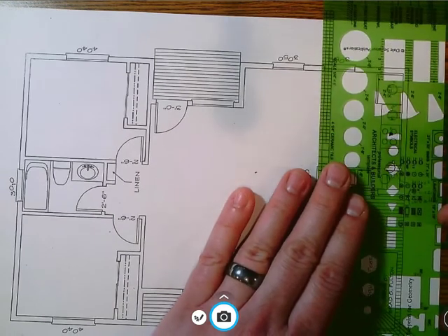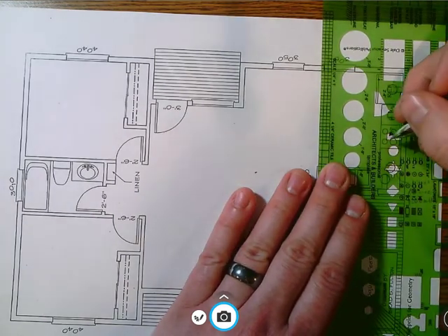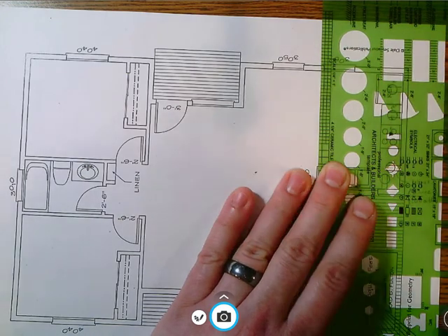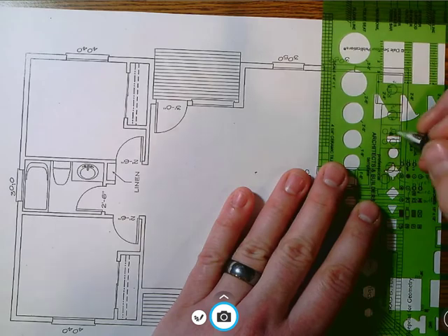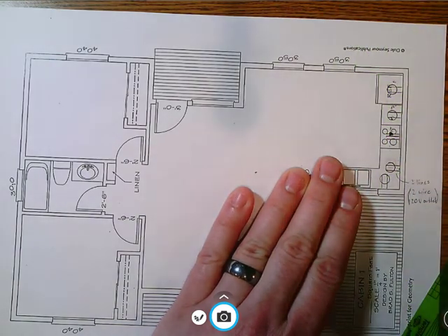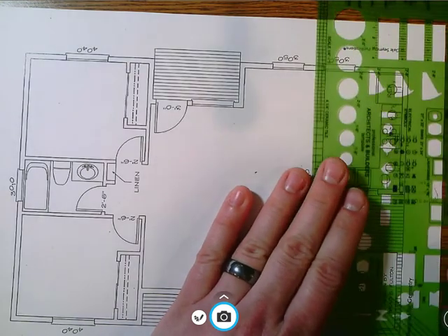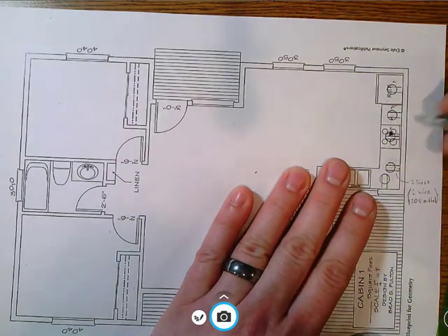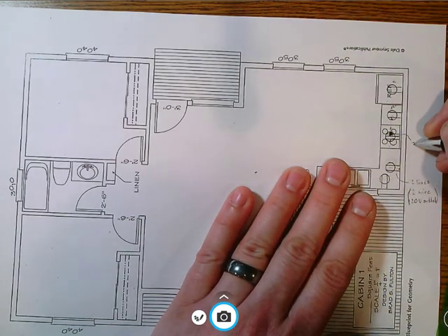Stoves require a little bit of juice. So what I'm going to do here is draw the 2 lines that I typically do. And how you designate it for an electrician is that you draw a 3rd line between the other 2 lines. You draw this 3-line sketch here, and then you take the circle and draw that there. Now here I have 3 lines, and this represents the 3-wire, which is part of the 240 volt outlet.